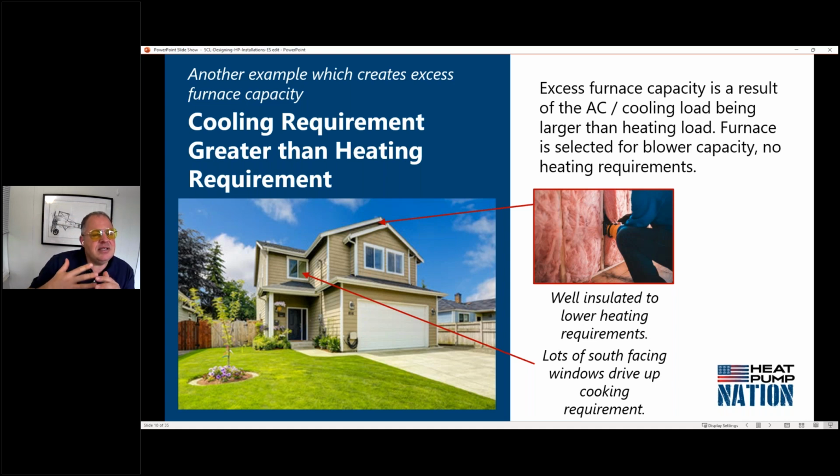And so there's this thing that happens for people like me who used to design heating systems for homes, where we need a larger capacity air conditioner than the furnace, believe it or not. But because the airflow requirements of that air conditioner require a larger air volume, you have to put in one of these large capacity furnaces because it just can move much more air.